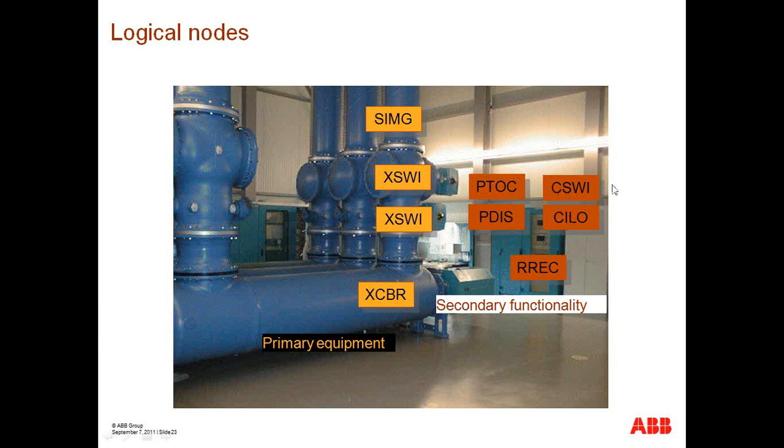And this is, again, a distribution of the functionality based on logical nodes, where we are now assigning functions to the different pieces of equipment within the substation. And it's all done within this intuitive addressing scheme, which not only includes a definition of the function, but also an association with the location of that piece of information within the substation.